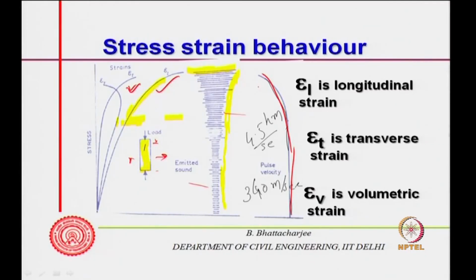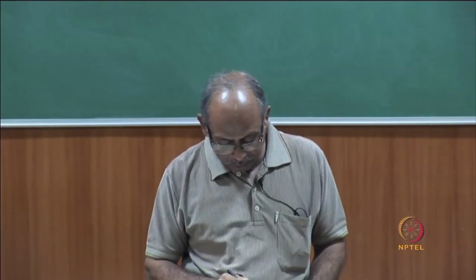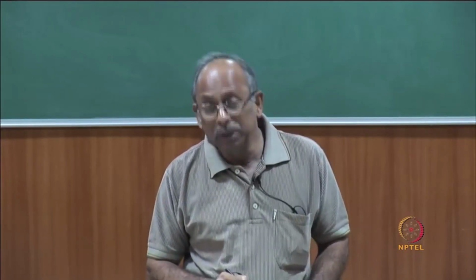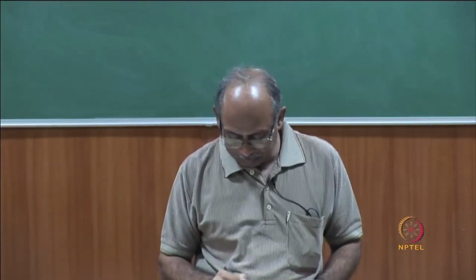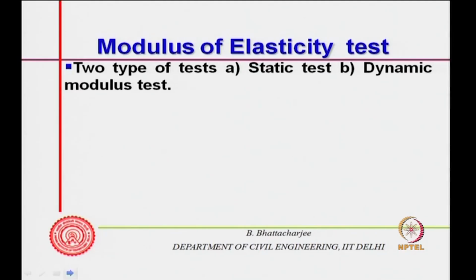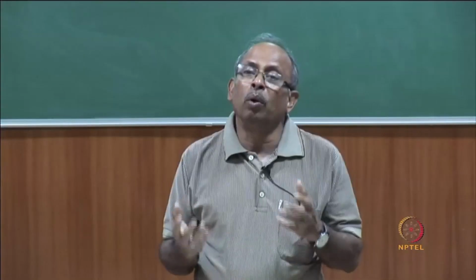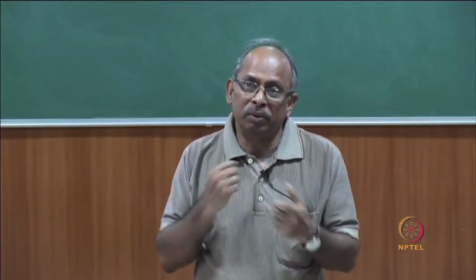So, the cracking of concrete is confirmed by this kind of testing. If I plot the stress strain curve, as stress increases with longitudinal strain, it shows that the nonlinearity of the stress strain curve is largely related to micro cracking of concrete, and so is the case with permanent deformation. This is the reason why you get nonlinear behavior as well as a non closure of the stress strain curve, that is, hysteresis.